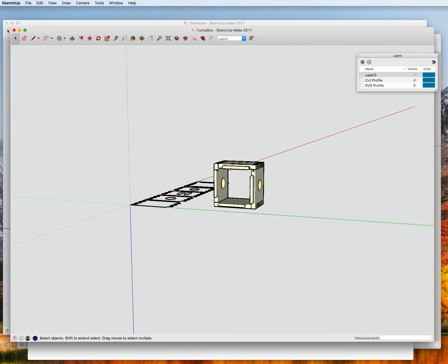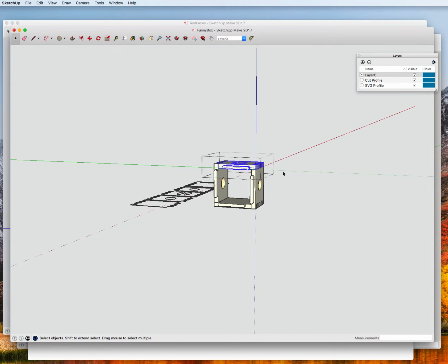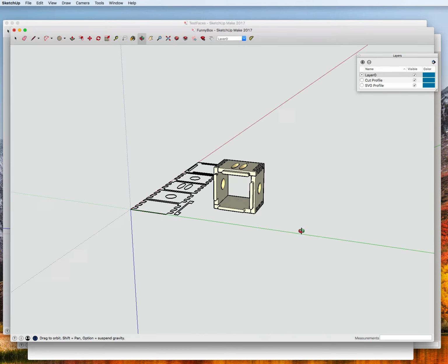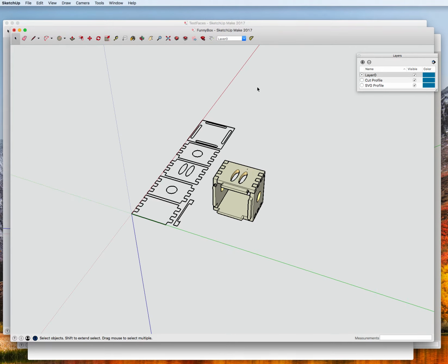It might be appropriate to go in and take this face and generate a profile for it. And so that's done that. And right now, the tool basically assumes that you have a material size of 24 inches by 24 inches. And so it'll lay things out, repeating and then moving along if you need more material. So it won't just keep on going in a line.